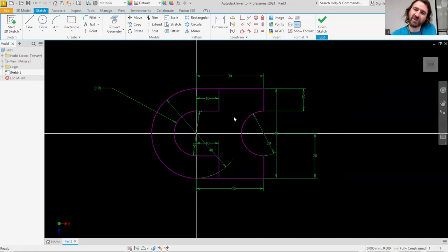Again, there wasn't really anything that changed when I added those dimensions in because we had locked pretty much everything in place. But because we trimmed the line that was the midpoint of this circle, it was saying, whoa, you eliminated the dimensions and the definitions, all the rules I was following when you cut that line, when you trimmed that out. That's why we had dimensions needed again, because that line that we were using the midpoint of was cut. That's the reason why the dimensions needed to be re-added if you were going for a fully constrained sketch.